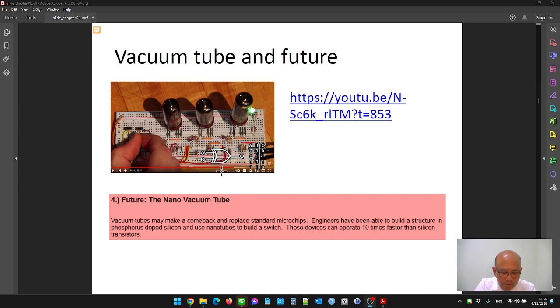This digital circuit has a function like the exclusive OR. The exclusive OR has two inputs, A and B, and Q for the output. The inputs have four combinations: 0 0, 0 1, 1 0, and 1 1. Only the inputs 0 1 and 1 0 generate output 1.